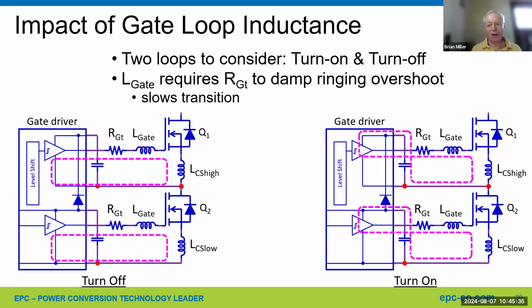And another thing that should help add some confidence is the gate threshold doesn't really drop with temperature very much at all. Definitely does with MOSFETs. So if you see something like a 25 degrees C spec on a MOSFET of, say, 1 volt, you would rightly get concerned because you would think, well, gosh, at 100 degrees C, that threshold's going down, the noise margin is gone, it's going to blow up. Versus GaN FETs, the same threshold voltage is basically the same at 25 degrees C and also, say, 125 degrees C. So the margin doesn't go away as temperature goes up.